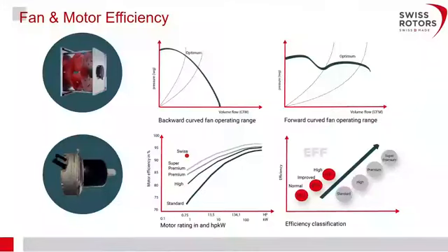If we look at those small diagrams, we can see that the EC motors which we have are with a very high efficiency, around something between IE3 and IE4. So these are the highest efficiency motors. Of course, with backward curve impeller fans, the optimum size is visible on the left diagram, and it is more stable across these changes than the forward curve fan operation, which can go to a different point of operation and can cause some problems.